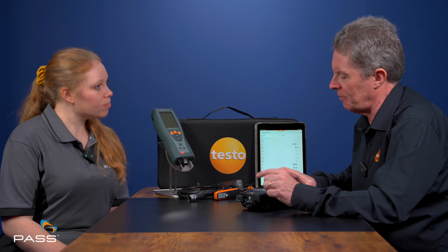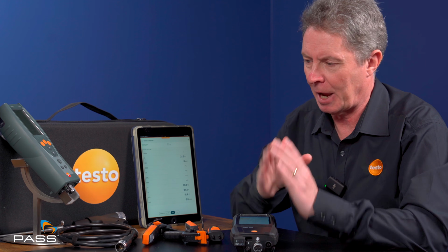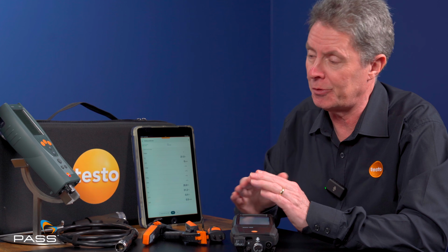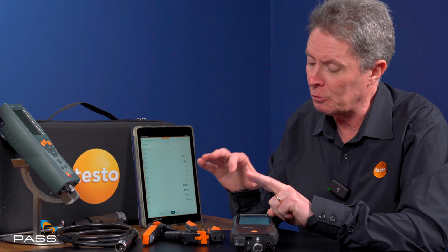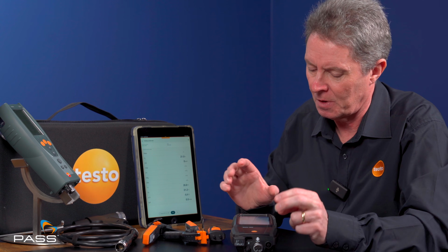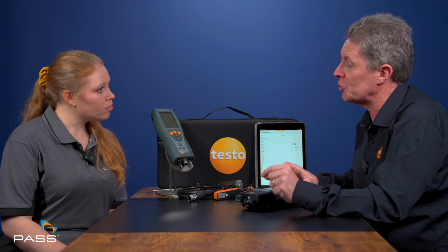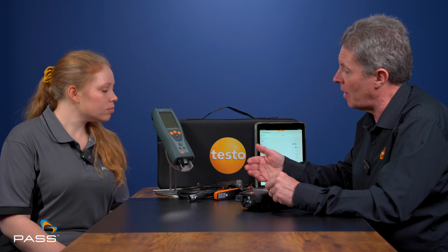Is that the total NOx value? So it is. With this sort of device, if you've only got a single NOx sensor, that's doing what's known as a calculated NOx measurement. There are two ways to do NOx, calculated and true measured NOx. To do true measured NOx, you need an NO and an NO2 sensor, and then the total NOx is a combination of those two values. With a calculated NOx, you apply a fixed NO2 percentage in the instrument, which you can input. Then you measure the NO, and you derive a calculated total NOx.